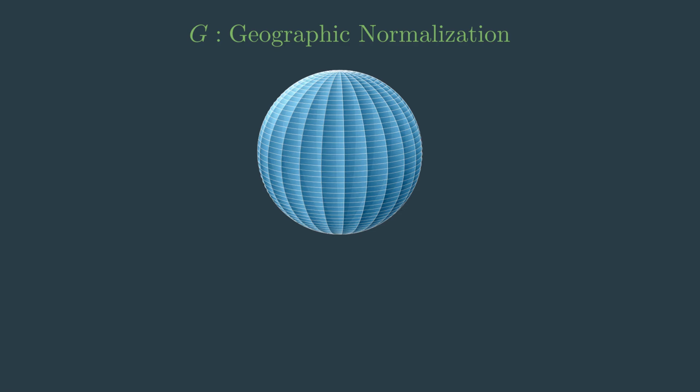Yes, it uses VLAT, the latitude of our street center point, and it relies on an accurate model of the Earth's shape, like the WGS-84 ellipsoid, to get these conversion factors, GLAT and GLON. Right. That cos(VLAT) term you often see in these calculations. It's vital for getting the longitude conversion correct, adjusting for that pole squeezing effect. Okay, so G applies these scaling factors, converting the meter offsets into degree offsets.